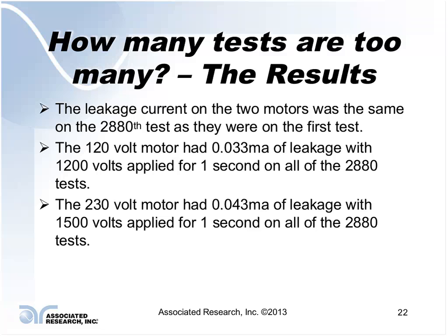He was taking these motors that had been Hipot tested essentially at sea level, and was trying to perform the same Hipot test at roughly a 5,000 foot altitude at the same test potential. He was experiencing some insulation failures where the motors were in fact breaking down.